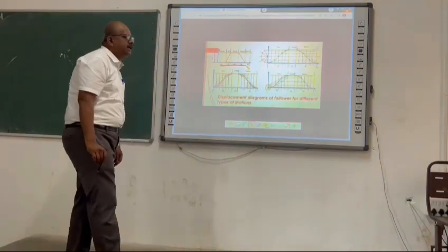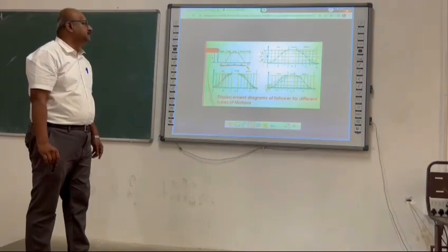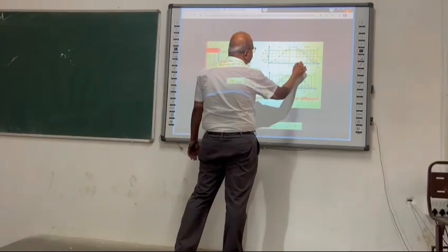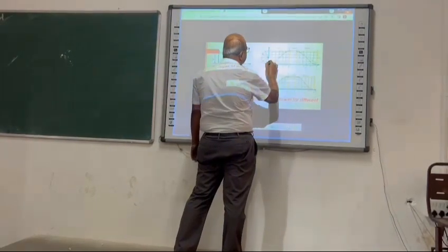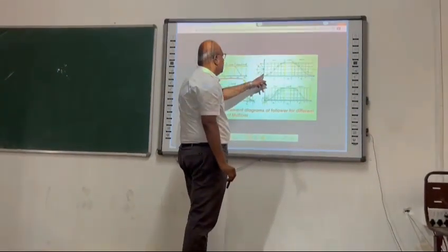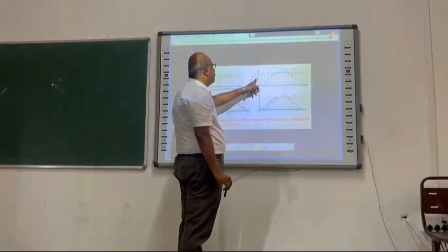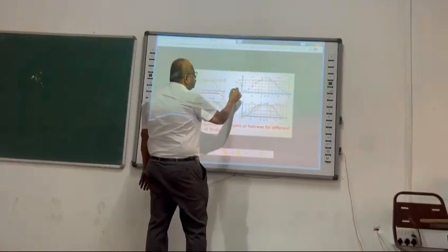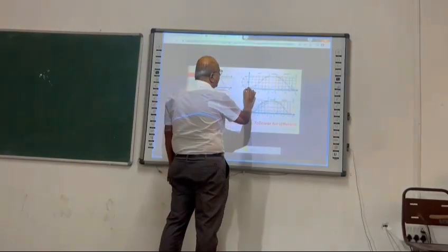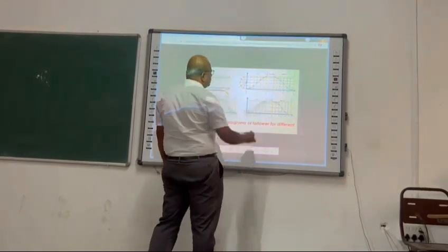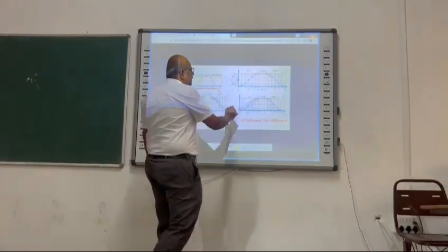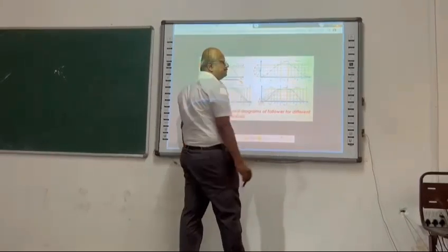Next one is the simple harmonic motion. For simple harmonic motion, first draw the x-axis of the cam angle and lift of the follower motion in the y-axis, and draw a semicircle on that lift portion. Divide the semicircle into suitable portions and the rise period into an equal number of portions, and draw the horizontal lines and vertical lines. You will get a smooth curve for rise.